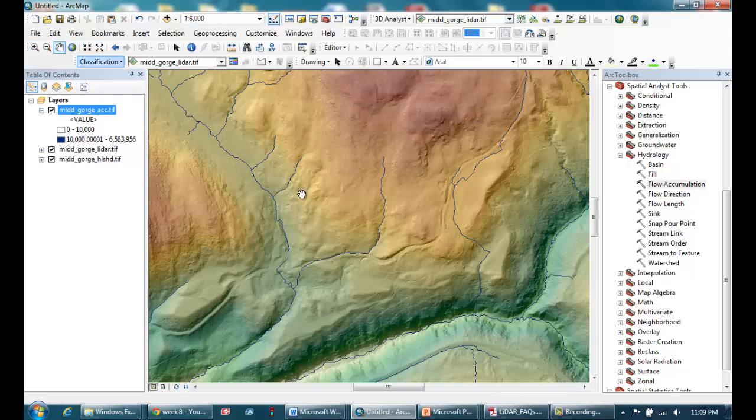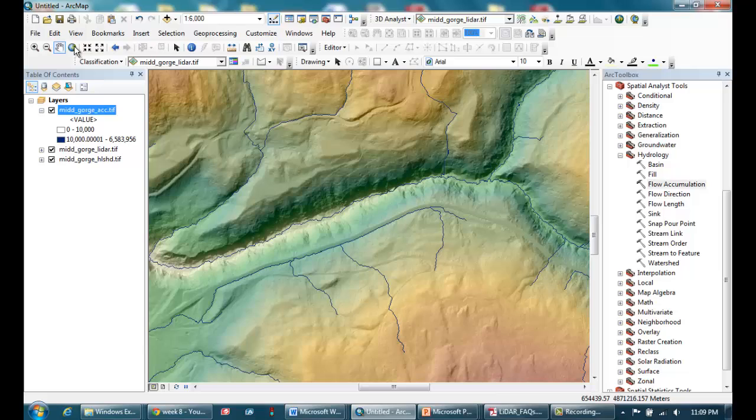And if you look around a little bit, we're going to see a bunch more examples of that. Take a look at the other side of the river. 3 brooks coming off the hill slope, each of them getting deflected at the main road and flowing down the main road. And in each case, there's culverts that actually go under the road there.